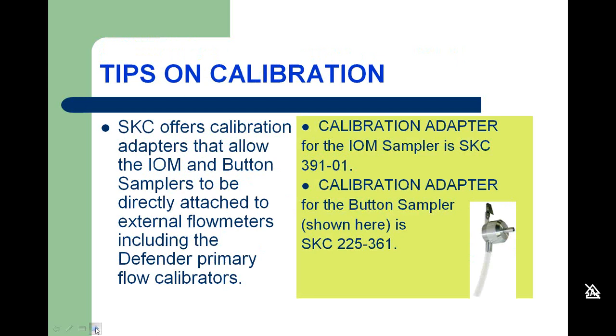It is generally preferable to use a calibration adapter to assist in flow measurement. SKC offers calibration adapters that allow the IOM and button samplers to be directly attached to external flow meters, such as the Defender primary standard.